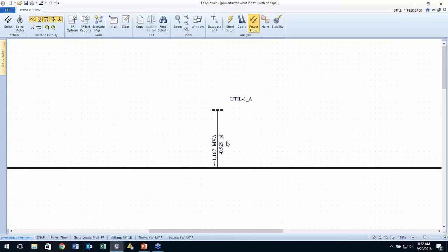Now you can see we've actually overdriven the power factor by having the capacitance in there. So the possibility, if the purpose is to reduce the power factor correction or power factor penalties, a partial solution would be to use VFDs. Bear in mind, though, that we're going to have to deal with the filtering because of the potential resonance.